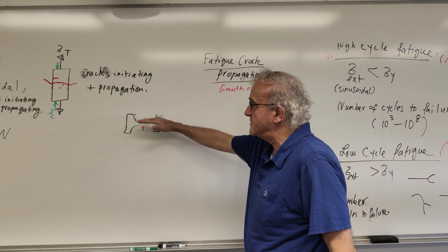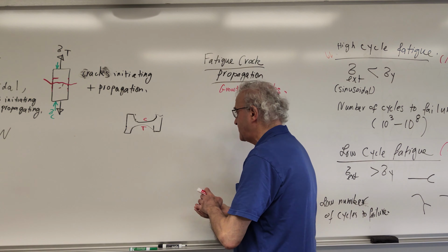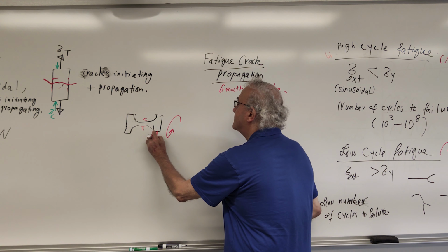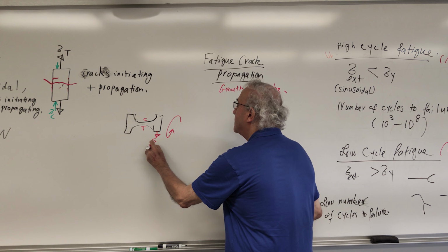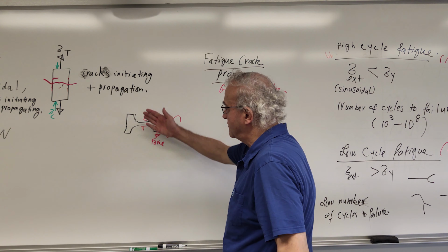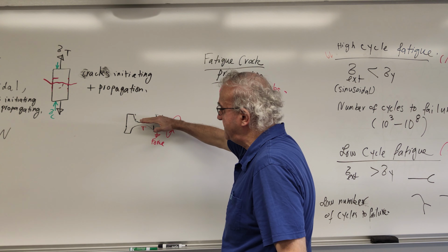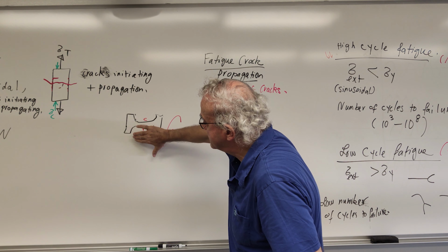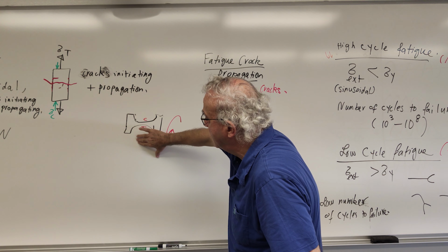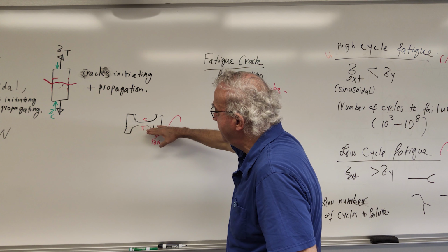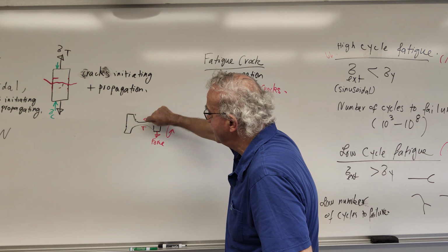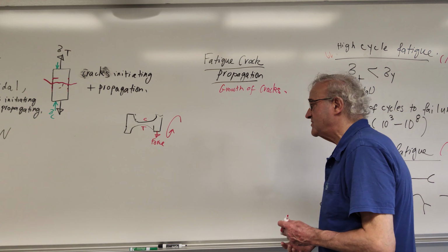But as the sample rotates 90 degrees, with a load here, the compression will become 0 and the tension will become 0. You rotate another 90 degrees, the compression becomes tension, and the tension becomes compression, then 0, then the sample which started with compression will go back to compression.